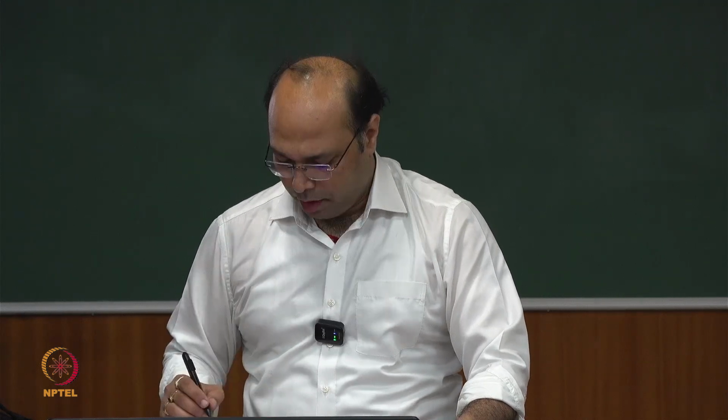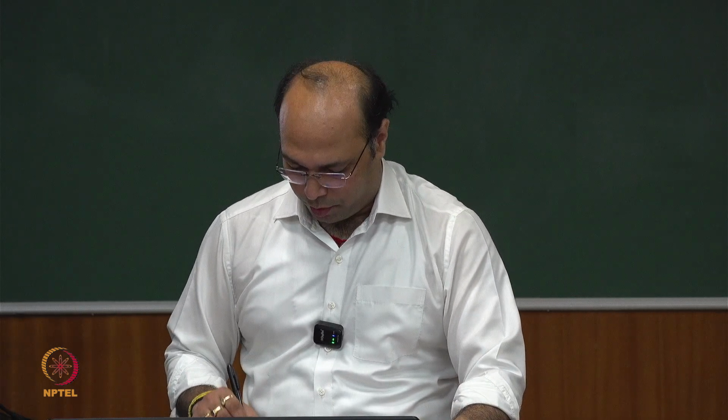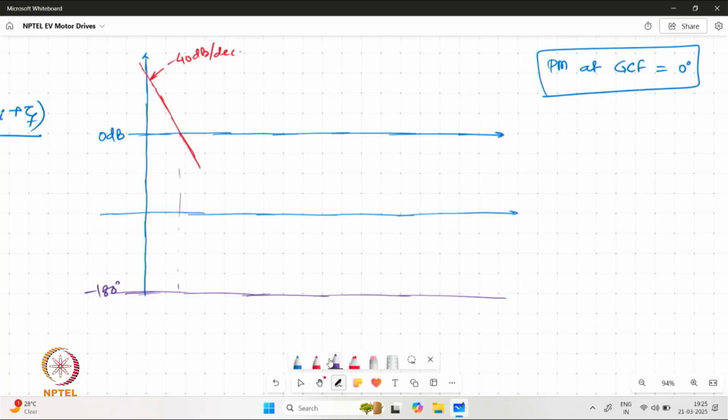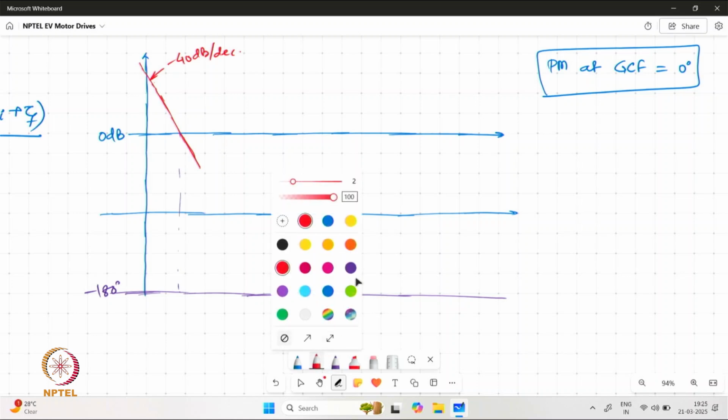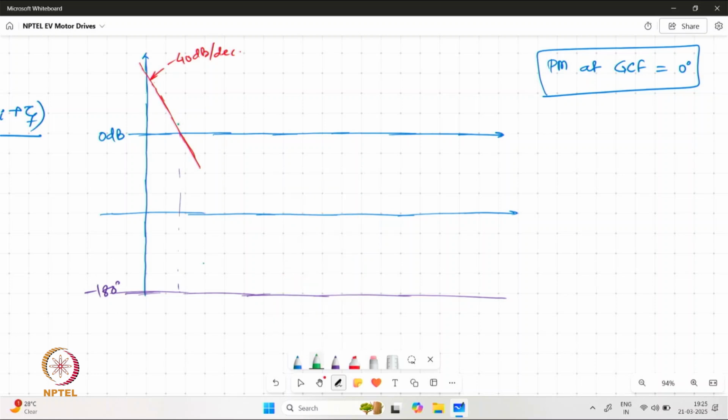on improving the phase margin of the system by positioning the pole and zero around the zero crossing of this magnitude plot. So we are going to locate our zero first, before the line meets the 0 dB line, say at this location.